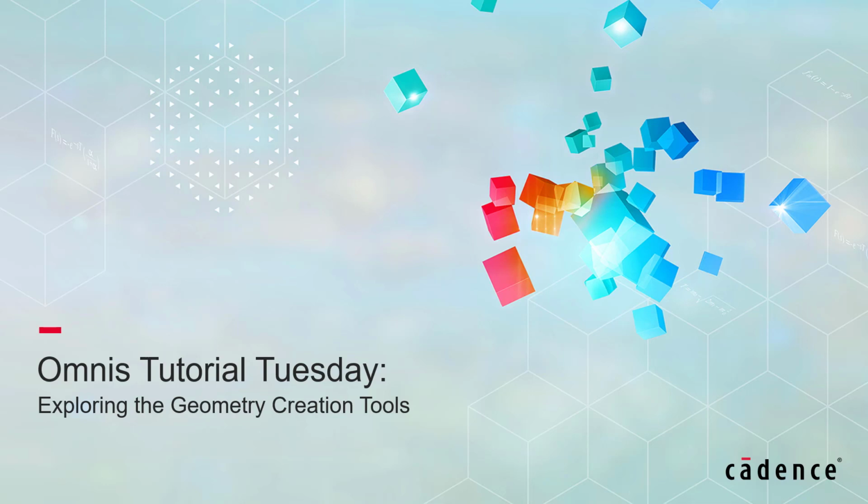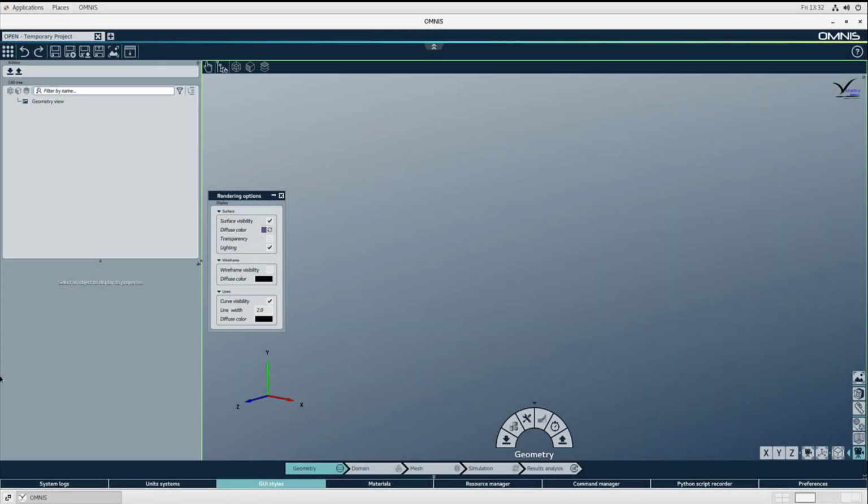In this video, I will show you how to create simple primitives using the Create toolbar. The Create toolbar is accessible from the geometry context using the second option in the pie. It allows the creation of simple 1D, 2D, and 3D primitives. Both 2D and 3D primitives can be used as part of the geometry domain or as refinement primitives during the mesh generation.